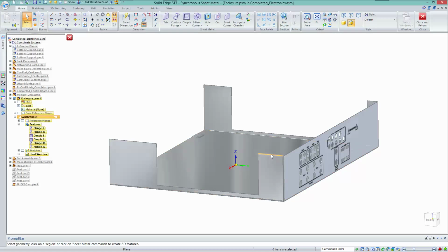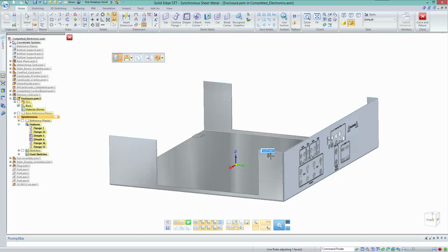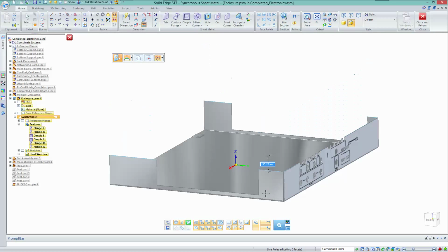One thing I'd like to do is drop down the height of this particular part of the side walls of this enclosure. So if I select that thickness face and start dropping these things down, what we'll find is that Solid Edge understands that all of the faces on top of this model are coplanar. So Solid Edge is allowing us to modify all of those. That isn't really what I want. I'd like to be able to modify this side and also the flange on the other side of the model as well, but nothing else.